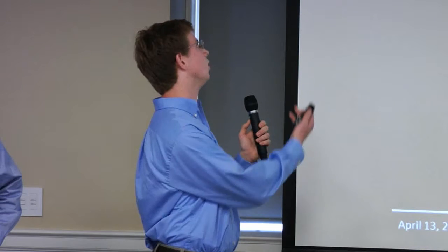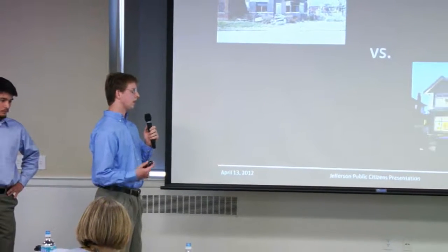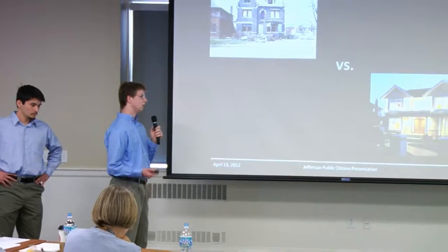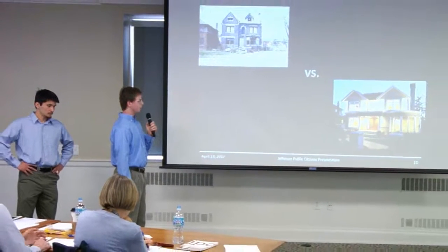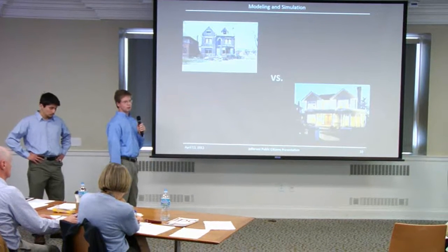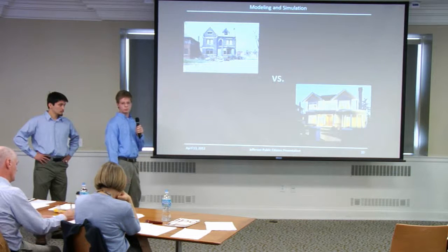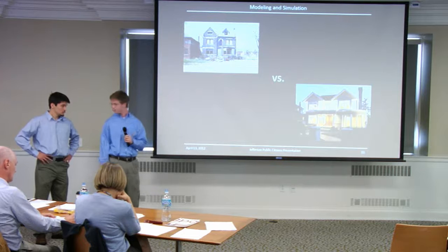Lastly, you have just the occupant behavior. You look at a home up in the top corner, it looks like it's hardly ever occupied, versus a home that seems to be occupied 24/7 with lights left on and TVs left on. Occupant behavior is a major component to home energy use, and so simulating the occupancy schedule is one of the ways we can consider ways to save energy. And from that aspect also, you look at an older home, the building envelope will be considerably less tight, meaning the building is more leaky and has less insulation, which causes more energy usage.